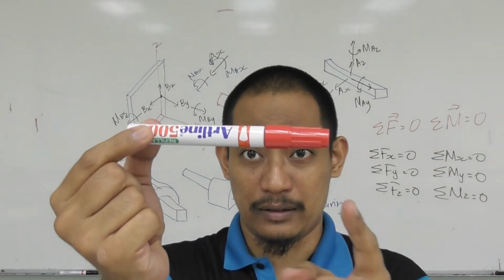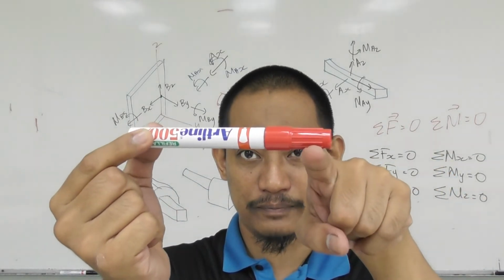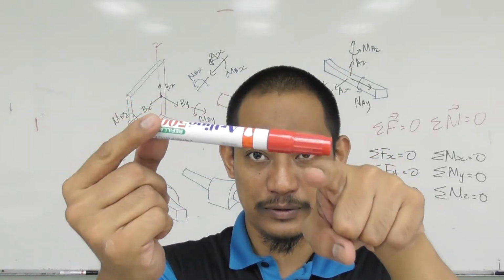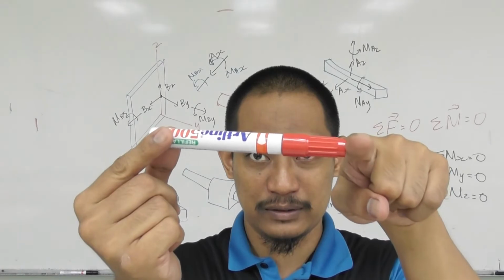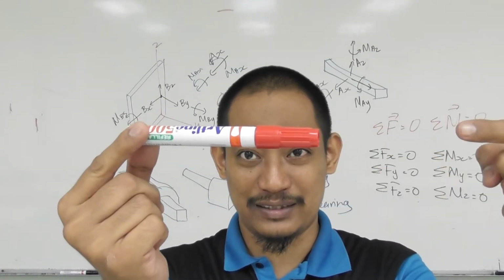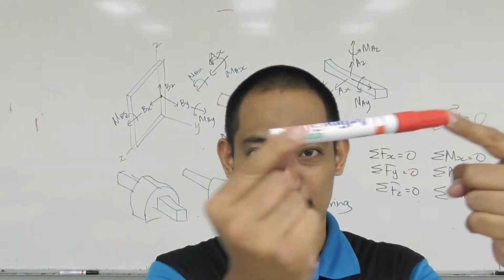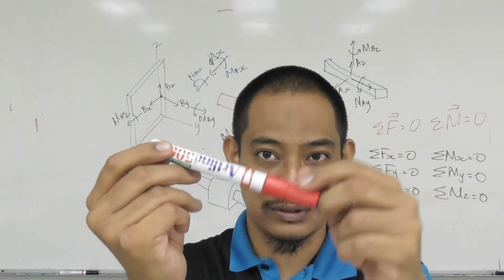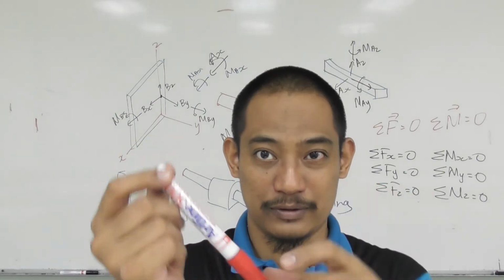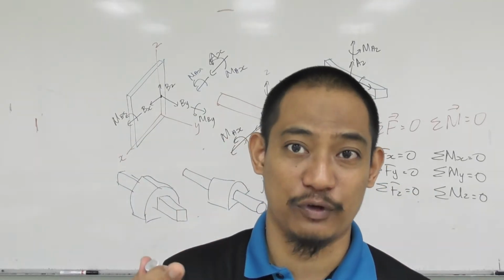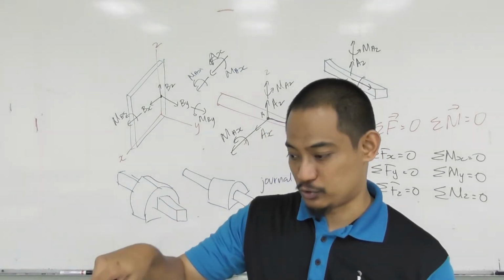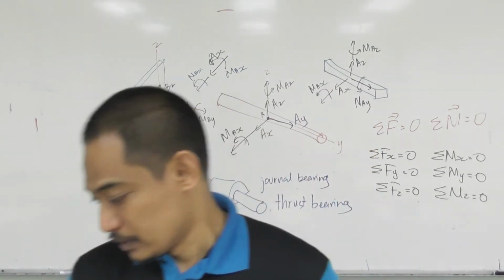And if you have a roller here, then this will be static, because the rotation is prevented by this roller. But if you have a roller here, where the normal direction is this way, you cannot go in that direction. However, this is not proper, because this will just go down, because nothing is preventing it from going down. So that's also a case of improper constraint. That's basically the example shown in the slide.